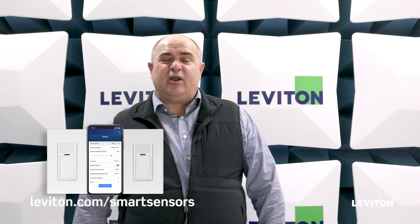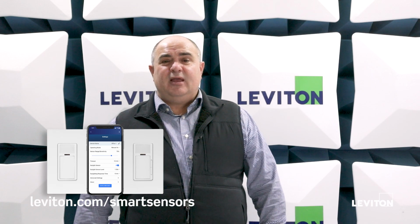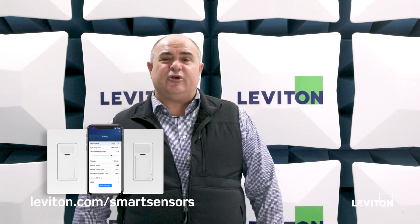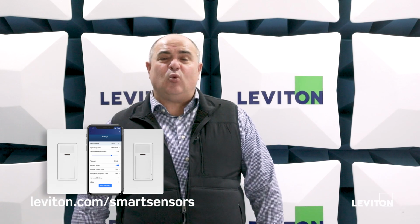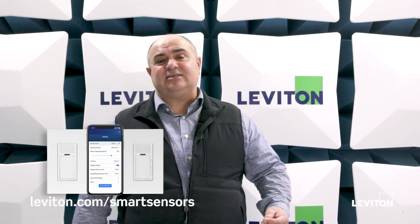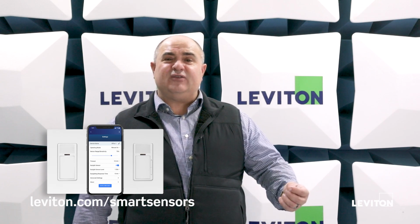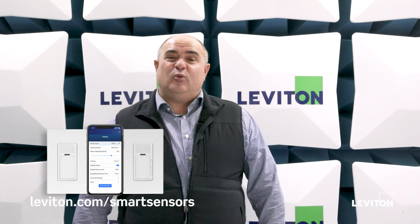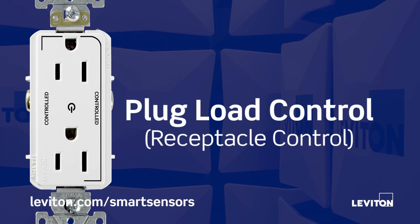Now you go, well, why would you want to do that? Well, in certain applications, we might have one fixture or the general lighting within the area operating on 277 volts. And then we might have possibly some pendant fixtures within the space or other decorative lights that operate at 120 volts. Well, as such, we could use two separate power packs to control the 277 one and then another one to control the 120. But even more, we can address the need for plug load control.